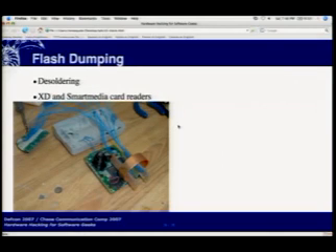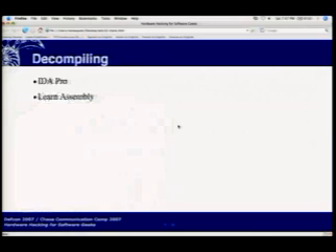The flash dumper thing I was talking about up there is for accessing more modern stuff, these 48-pin, thin small outline package flash chips. It turns out that XD cards for cameras and smart media cards for cameras are basically NAND flash in a funny package. They're exactly the same interface, and you can use one of them to build a flash dumper that you can just clip onto the chip and, depending on the electrical characteristics of the board, dump the flash via a USB cable.